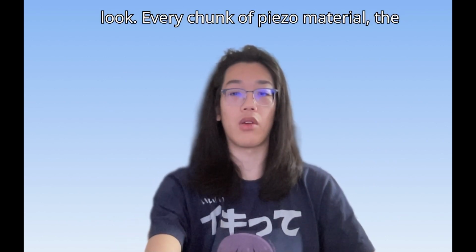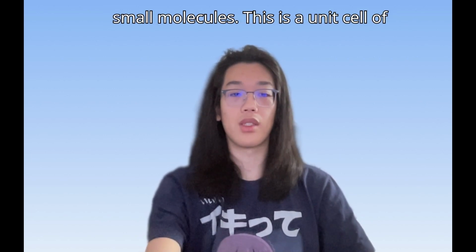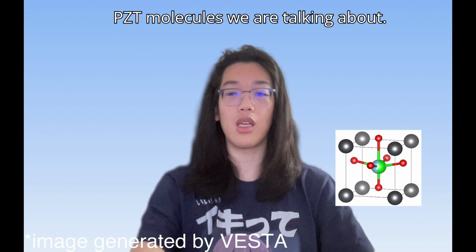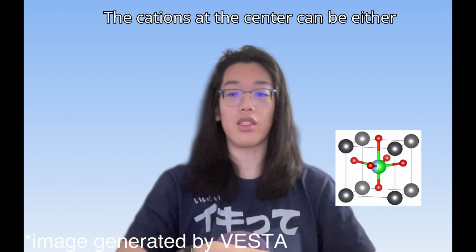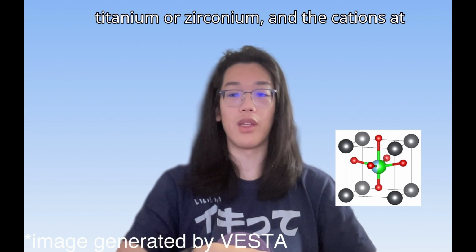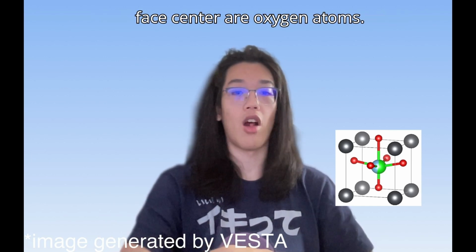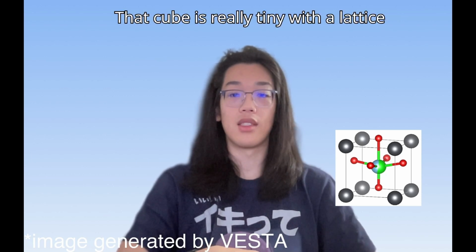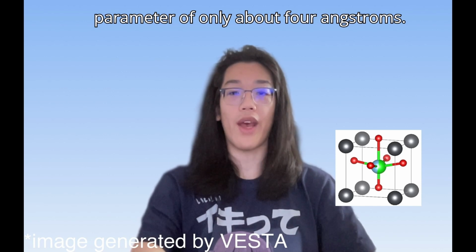Every chunk of piezo material, the piezoelectric material, is made up of small molecules. This is a unit cell of the PZT molecules we are talking about. The cations at the center can be either titanium or zirconium, and the cations at the corners are lead. The anions at the face center are oxygen atoms. That cube is really tiny, with a lattice diameter of only about 4 angstroms.